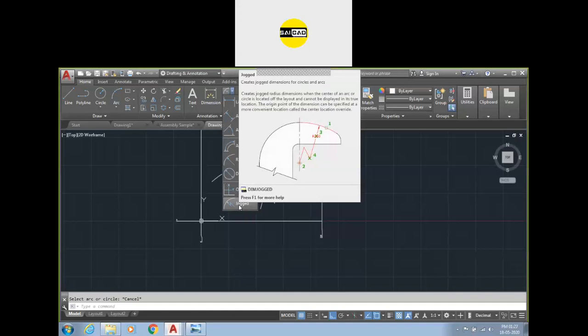Okay, so right now you can see the red arc. If you see the red arc inside where one is written, its center is far away from the layout. It's outside of the layout. We cannot specify the exact center in our sheet. So to show the center, and the value of the radius is from center, we create a dimension called jog. With the help of jog, we will create a new center point from where we are going to specify the radius. Okay, it's not the exact point.